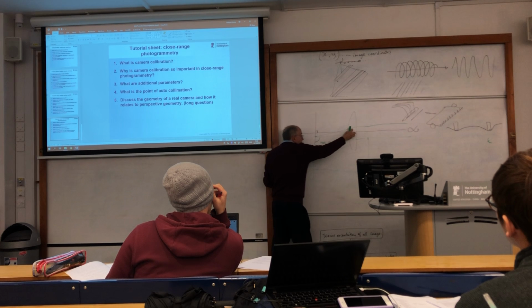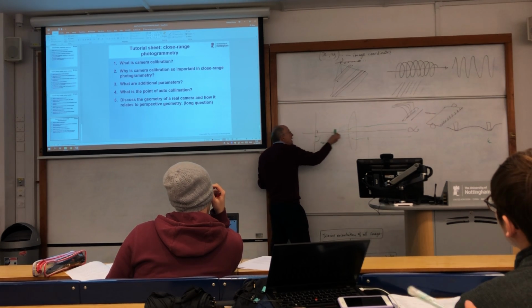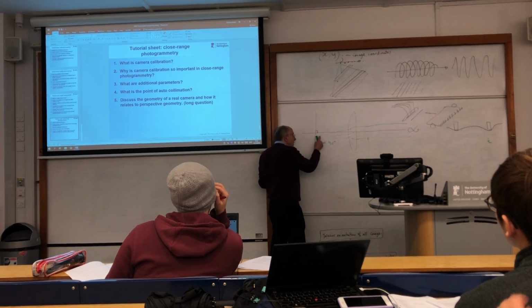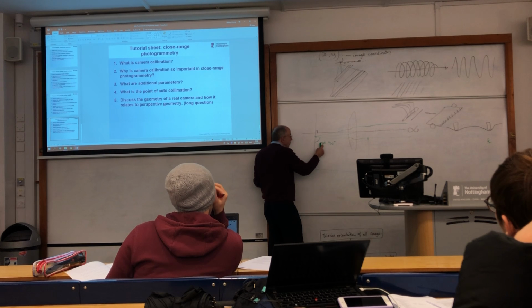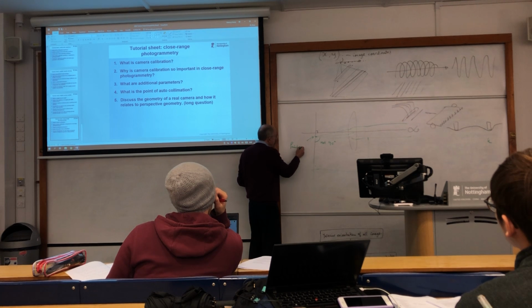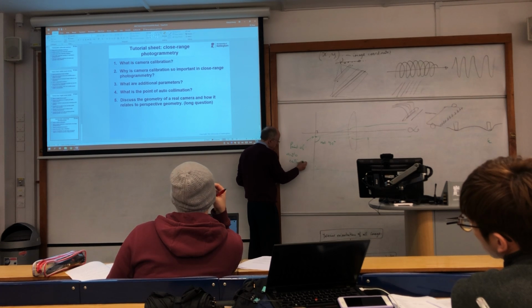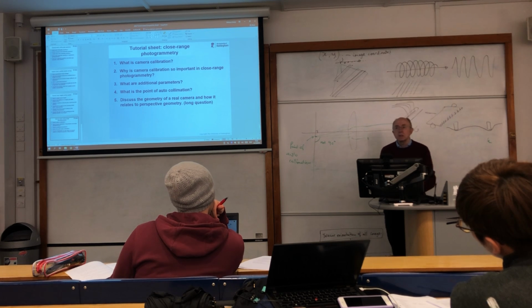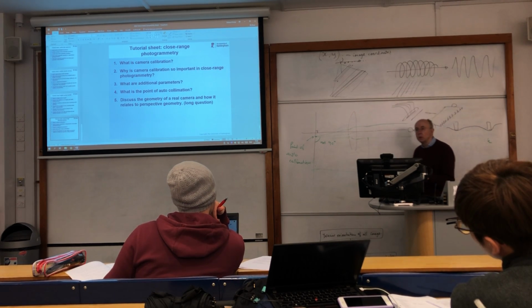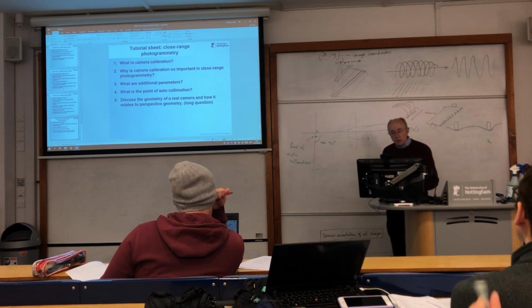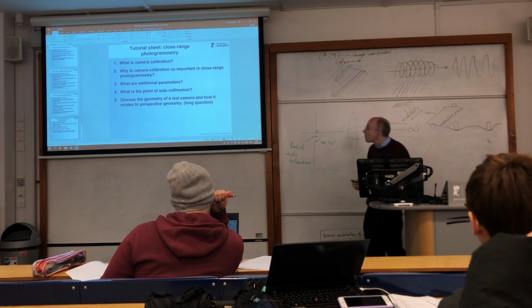On the real camera, they come through and they focus somewhere else, even though they're coming in perpendicular to the focal plane. This chief ray here is not 90 degrees. That is the point of autocollimation, and that is the point that is normally considered as the best estimate for the principal point. Okay? The best estimated position of what we consider to be the principal point.